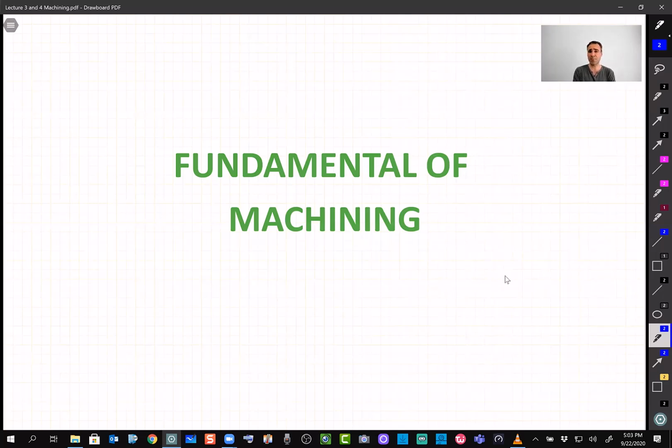The machining process can be automated, but it is still advised as a good process for lower quantity, not for making large numbers of parts, which we will discuss shortly. Also, many other processes such as forging, casting, or powder metallurgy still depend on machining, because after making a part by forging or casting, the surface quality may not be satisfactory, and we have to do an extra process, which can be machining. All right.